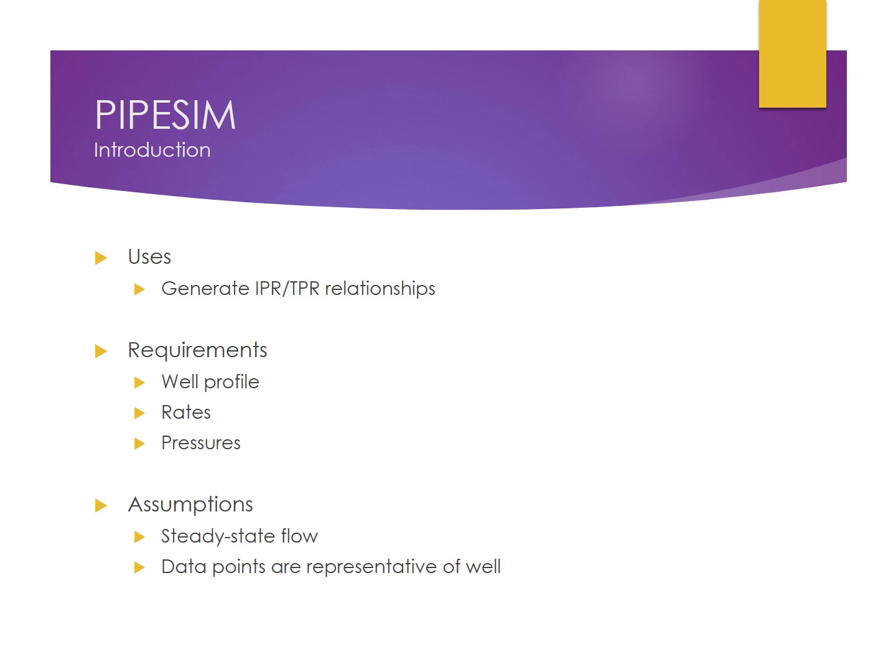The program we are using is PipeSim nodal analysis, which we will use to generate the relationships between IPR and TPR curves. The requirements for the simulation include well profile, production rates, and pressures, just to name a few. The assumptions we are making are that flow is multi-phase steady state, and that the data points we receive from our industry contacts are representative of the well.